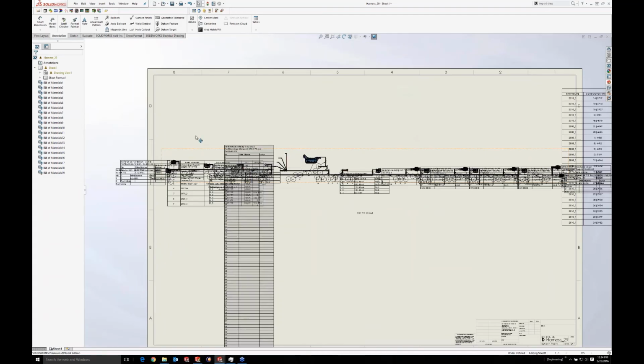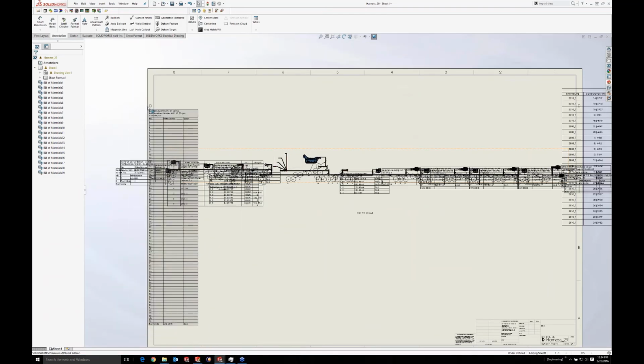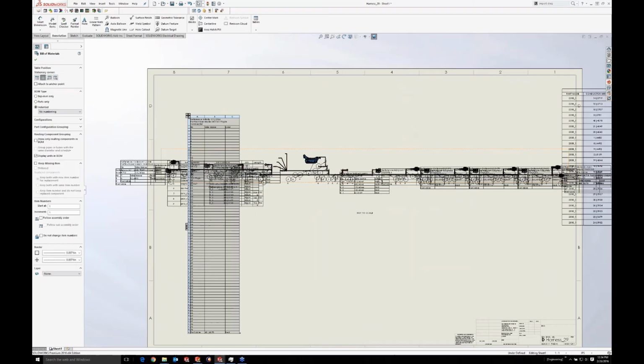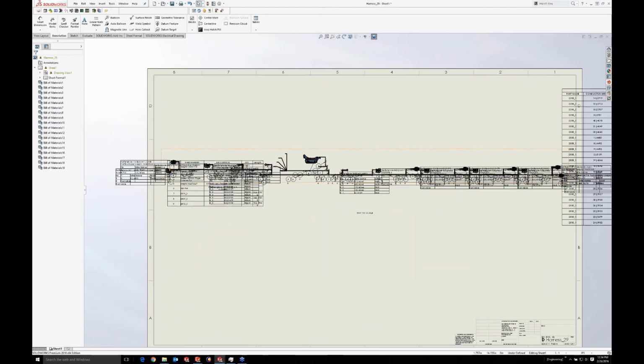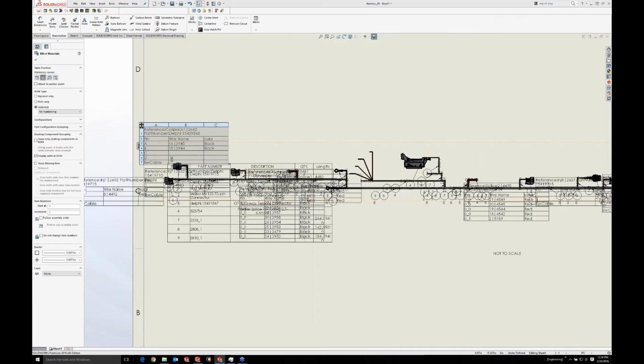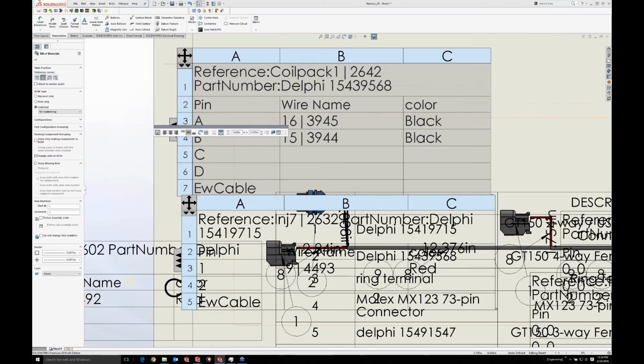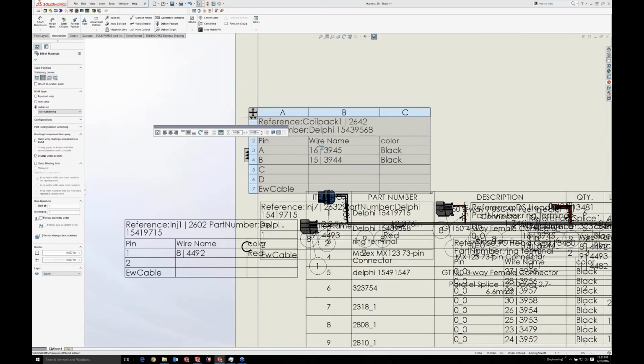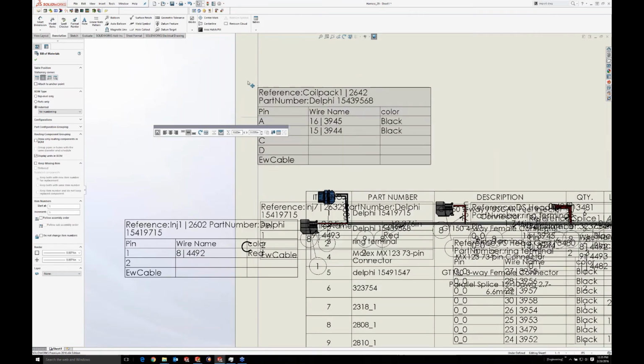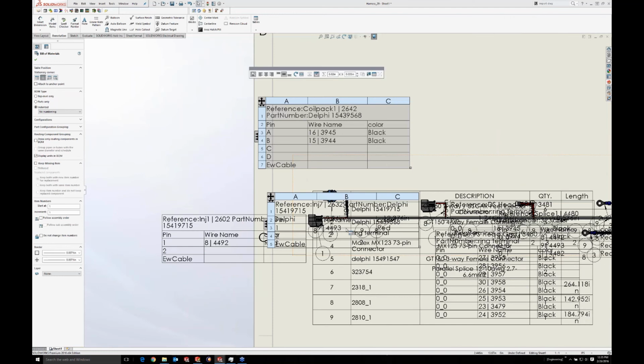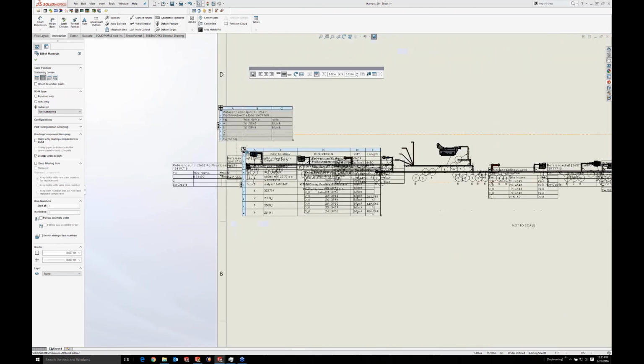Once I saw this, this looks like a heap of confusion, but once you realize what all these tables are, this is the connector table for my 73-pin connector. So maybe I don't need that guy. But here are some of my other connector tables for these individual connectors. I'm going to zoom in so you can see that. See, it's highlighting that connector and then showing me it's a 4-pin connector and it's routed a couple of these wires. Not every connector is fully populated.